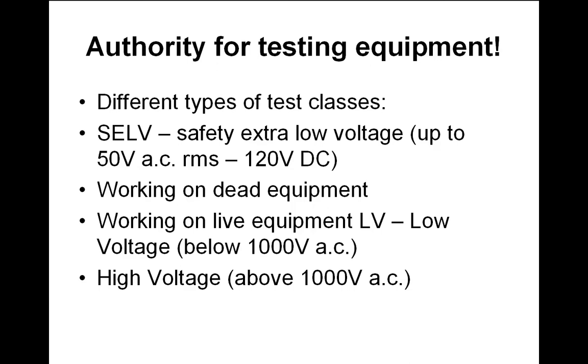And I'm not sure whether I did this with you, but when I've got my insulation tester, I tend to do an experiment where I put the probes really close to one another, but they are not touching. At that point, you can actually see arcs coming over. If it's dark and you look at them, you can actually hear it. You hear this crackling of the sparks, and you can see a little arc as well. And this only happens when you go up to 1000 volts. At 500 volts and 240 volts, less so, if not at all. So high voltage is above 1000 volts.